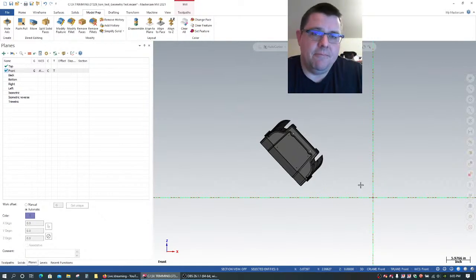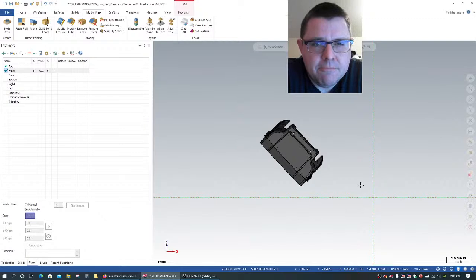When people say that you shouldn't move the geometry, unless there's some reason for that, like we create a local origin point and a local axis coordinate system on the part, and then we program from that 0 point because we need to be able to bring in the part for revisions quickly, then I agree.